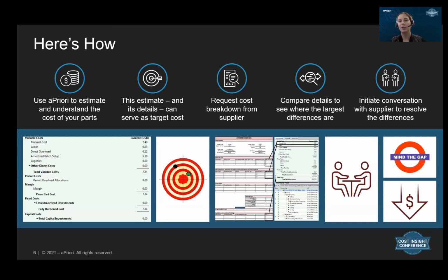Finally, keep in mind that you may uncover something that you as the buyer need to do differently. For example, I worked with a supplier who said, our machining time is longer than your estimate. The longest step in the machining is keeping this height tolerance on the part. If you could relax that, then we could reduce the time. And I knew that part had to fit into a housing and it was tight width-wise, but not height-wise. So the engineer agreed to relax the tolerance.